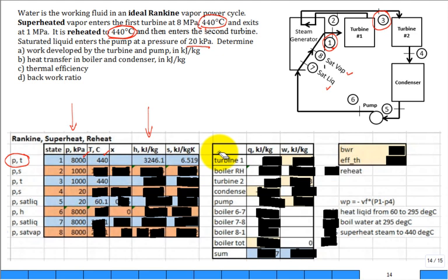And then, once I know that it's the best turbine, it's going to be no entropy generation, adiabatic, so in a second law analysis, the exit entropy is equal to the inlet entropy. True? Then guess what S2 is? Now I've got S2 figured out. I've got P2 figured out. Pressure and entropy fix the state.